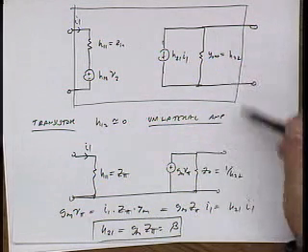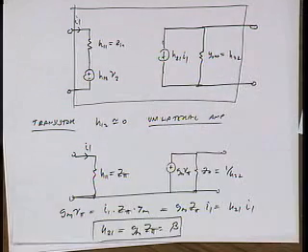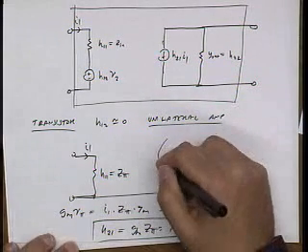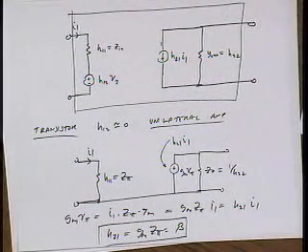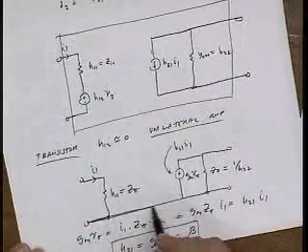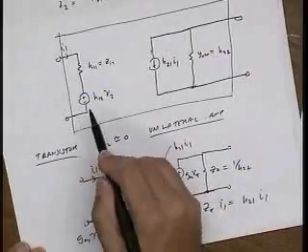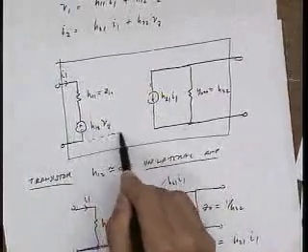Anybody want to point out a difference between this transistor model and this hybrid pi model here? This hybrid pi model and this general hybrid equivalent circuit. Yes, Christian. I think you mentioned this earlier about how the two ports are connected together. Yeah, very good. So here I have a short across here, right? So these terminals in this general model are not connected.